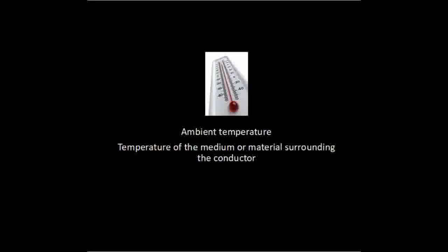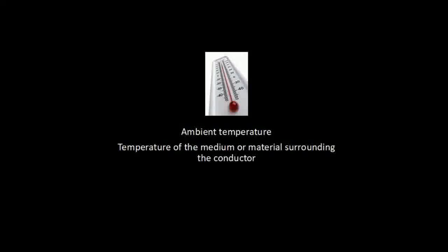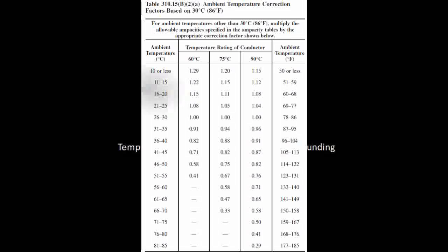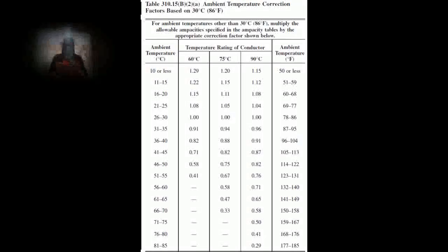Temperature of a material. A fourth consideration in conductivity is temperature. Most metals used in conductors such as copper and aluminum increase in resistance as the ambient temperature rises. Ambient temperature is the temperature of the material surrounding the conductor, such as air, water, or soil. In many electronic products, careful design is necessary to ensure proper ventilation and radiation of heat from the current carrying conductors.